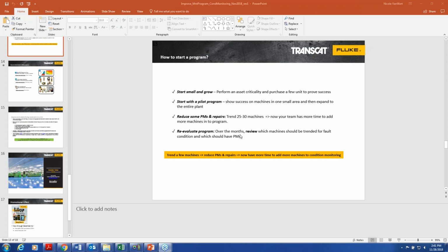We don't have wireless in our buildings. Can we still use condition monitoring tools? The answer to that is yes, you can, if the data from that tool can make it into a computerized maintenance management program or an enterprise asset management program simply by manual entry. So we can use our handheld tools to go take a reading and enter that data, or many tools have the capability of storing that data, and then when we do get connectivity with that tool, we can actually upload it once we get into an area that we have connectivity.